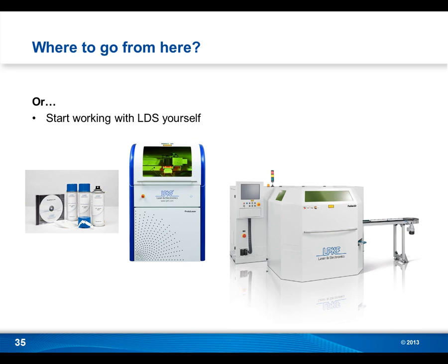Yeah, so maybe a few more notes on the prototyping process. We're talking about the laser for the circuit structuring, but also the plating itself. We mentioned earlier in the webinar this is electroless plating, and electroless plating is not a too simple process in the mass production world. But one part of this prototyping package that we're about to introduce is a very simple and easy to use plating method, something that can be used in any type of lab environment, because that's a bit of the missing link to make this technology quickly available for any engineer. So this is a very big portion of making this very simple to use, not only the laser part but also the plating as well.